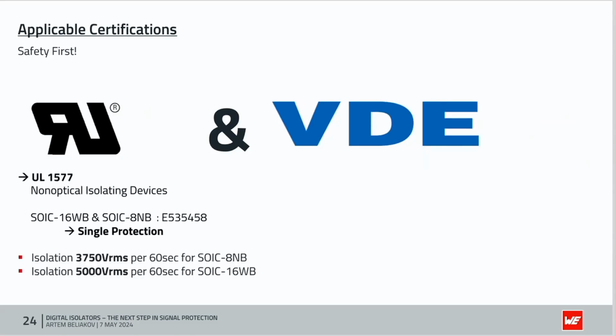According to UL 1577, our digital isolators in the SOIC 8 narrow-body package provide isolation up to 3.75 kilovolts RMS per 60 seconds and 5 kilovolts RMS per 60 seconds for the SOIC 16 wide-body package.